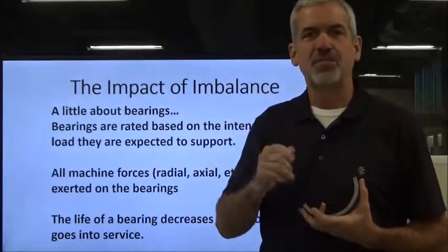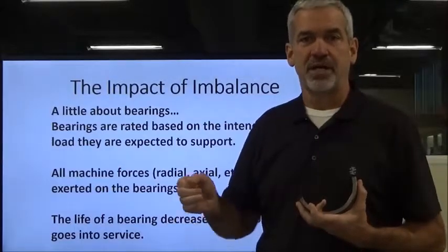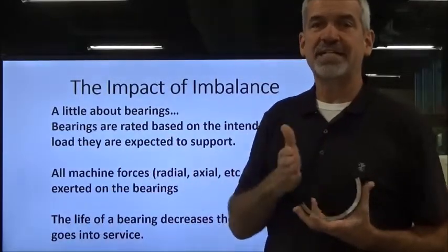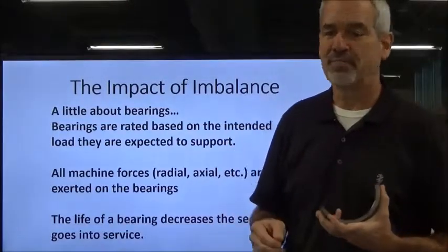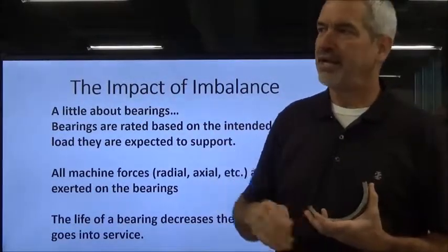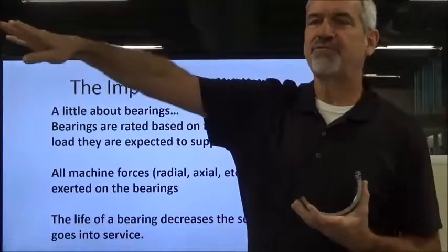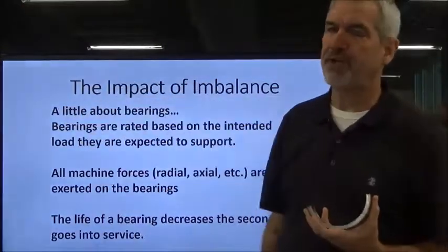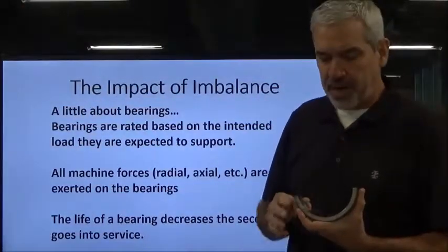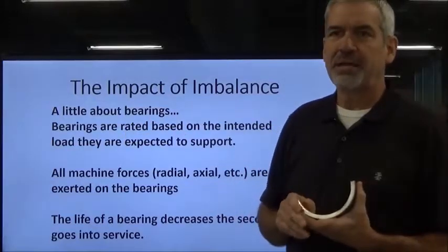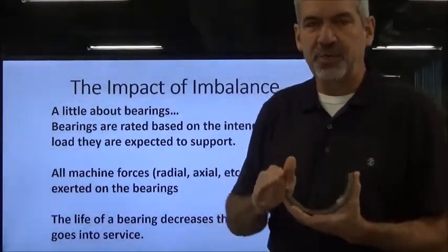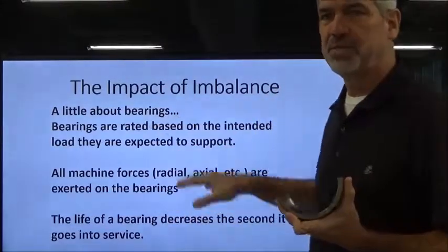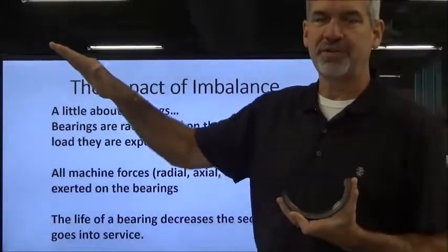I said, "Tell you what, we're going to leave this machine shut down." They were already finished, and I needed to take some baseline data, but I thought I'd wait and take it Monday morning. So we left the machine locked out, and the other 4 blowers were running over the weekend. I went home and came back Monday morning, and said, I've got to take that baseline reading and get a good reading of what a good bearing looks like on this machine, so we can start trending it through failure.